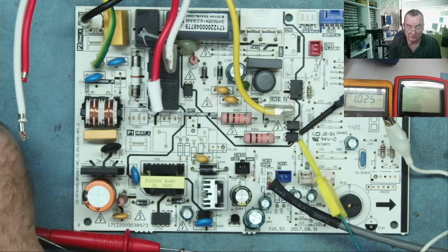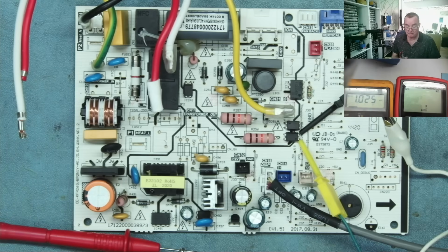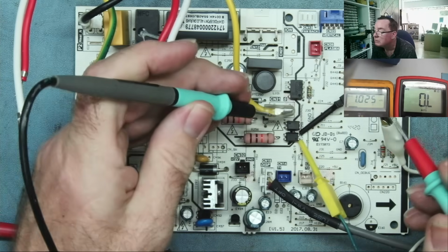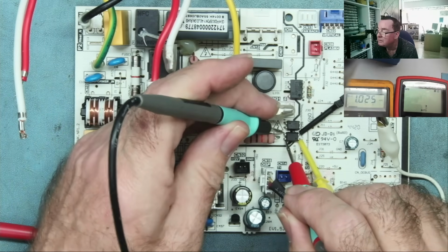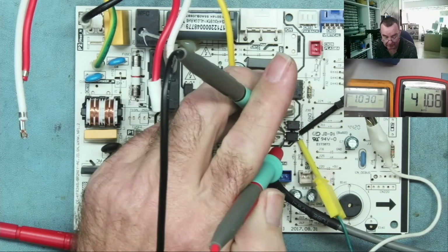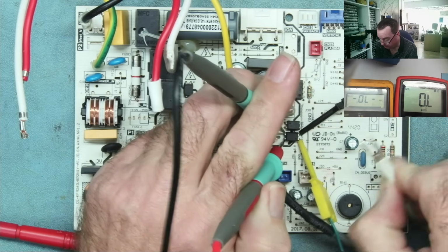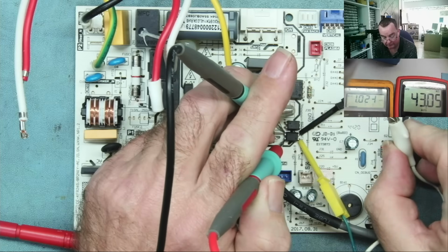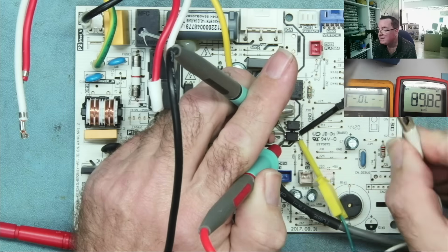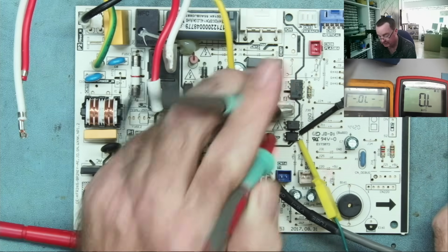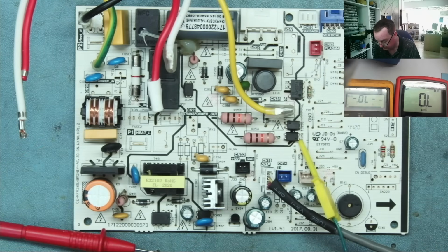Now, take another multimeter. We all need more than one multimeter, remember. Ohms range. And measure across the transistor. You'd expect this is probably collector emitter. And it reads 4K, yeah? Now, disconnect this. It's open. 4K, yeah? Or 41K rather. So we can see that it switches the transistor, okay? That's probably a good optoisolator. At least we can say it works, okay?